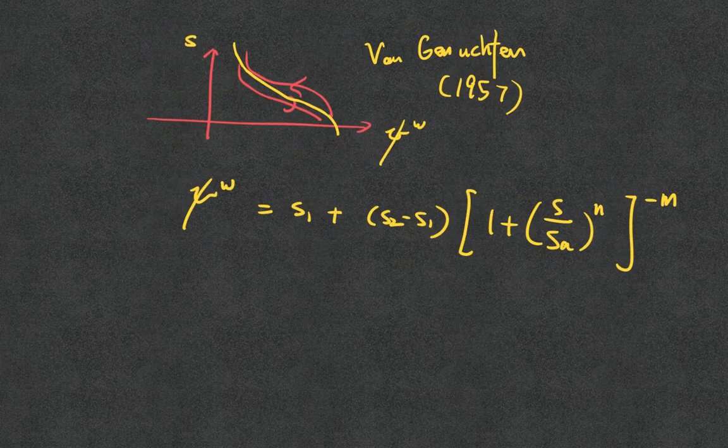So let me explain what S1 is. S1 is the suction at which, if you increase further, it won't change the degree of saturation. And S2 is the endpoint where the degree of saturation is the highest. Oftentimes you set it to 100, but sometimes not. There's also another possibility that no matter how little suction you have, you will still have some residual bubble that you cannot get out. Or maybe oil.